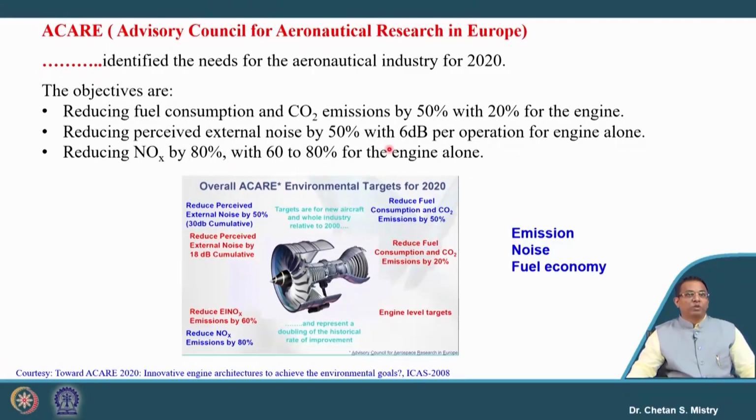Their objectives: reducing fuel consumption and CO2 emission by 50%, with 20% for the engine. Second, reduction of perceived external noise by 50%, with 6 decibels per operation for the engine alone. Next, reduce NOx by 80%, with 60 to 80% for the engine alone.